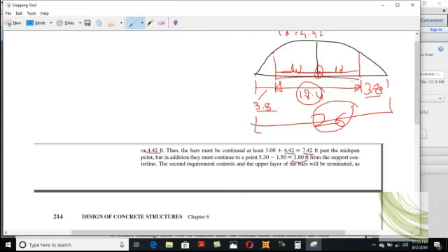Okay, so if the embedment length is reduced to some amount of feet, it should not be less than 7.4. These 8 number bars should be embedded into the concrete to both sides for a distance of 7.42. Clear? And now I think this criteria is fulfilled.